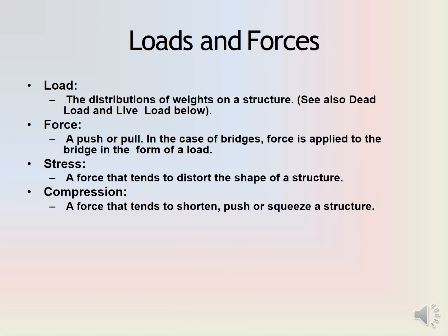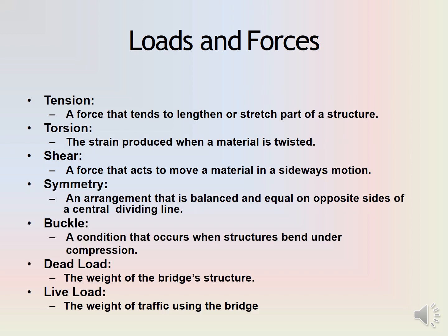Loads and forces. Load is the distribution of weights on the structure, in the form of dead load as well as live load. Force: a push or pull. A force is applied to the bridge in the form of a load. Stress: a force that tends to distort the shape of the structure. Compression: a force that tends to shorten or push a structure. Tension: a force that tends to lengthen or stretch part of a structure. Torsion: the strain produced when a material is twisted. Shear: a force that acts to move a material in a sideways motion.